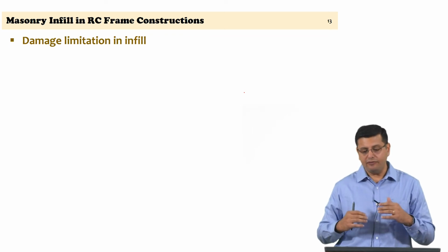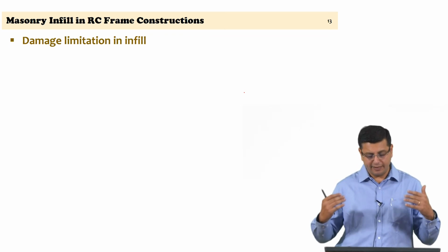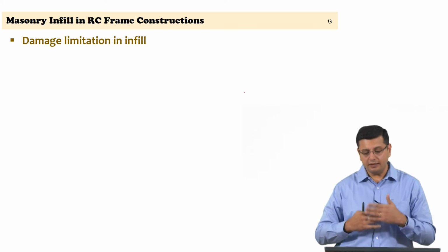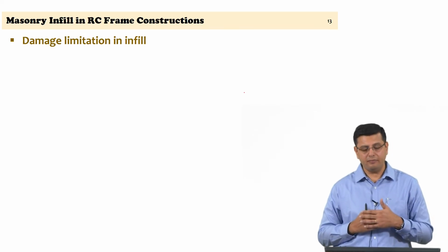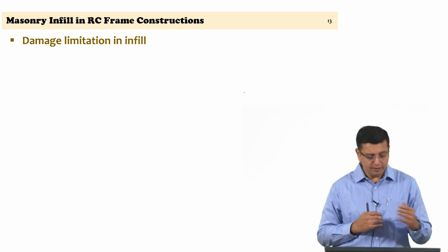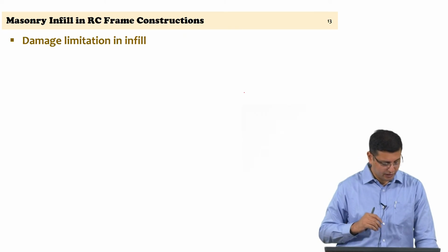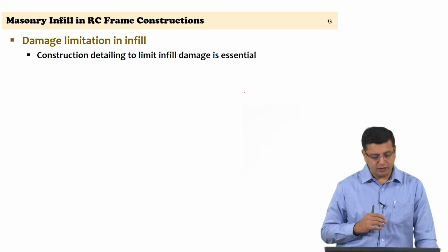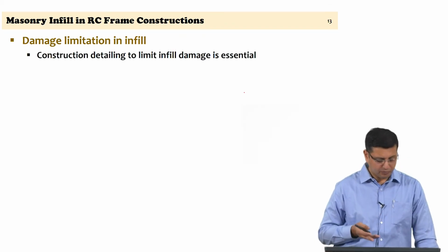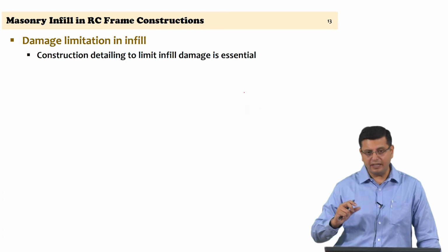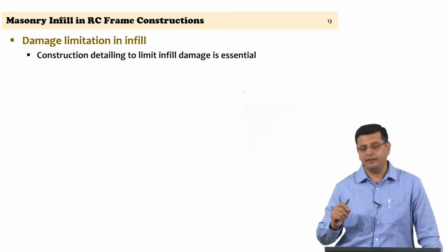So, if the panel can be retained within the reinforced concrete frame, then a certain limit state can be achieved, particularly the life safety limit state against falling hazards. So, recent works have looked at bringing in construction detailing to limit infill damage.